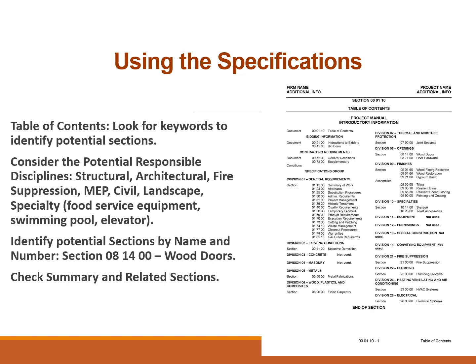You'll see in the left-hand column a reference to section 081400 wood doors, and you'll notice the 2, 2, and 2 combination for the numbers. Now, CSI is remiss because they don't provide a specific format for the number. They say 6 numbers, but as far as CSI is concerned, you can use all 6 numbers together, 081400, or you can do a 2 and 4 combination, 08 and then 1400, where you separate the division from the actual section element, wood doors in this case.